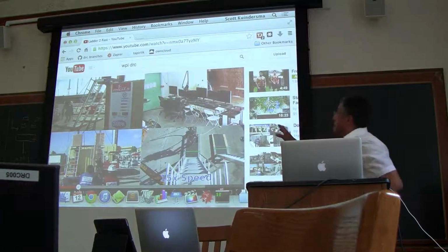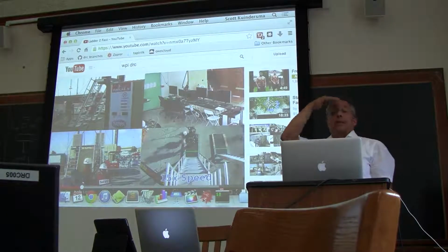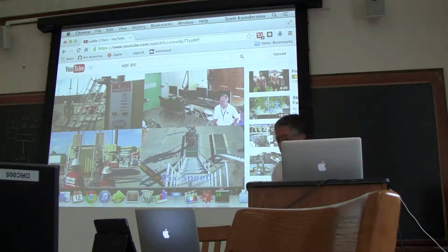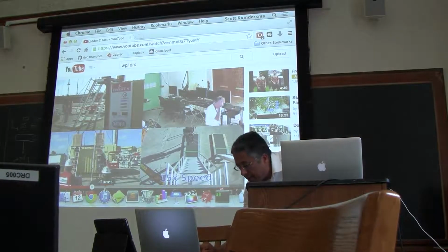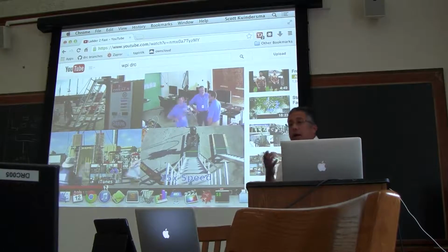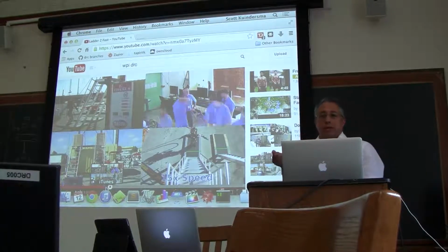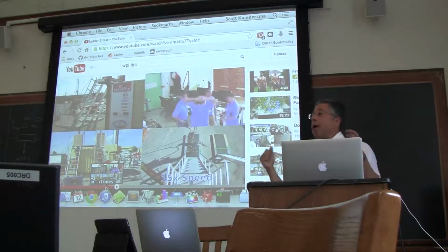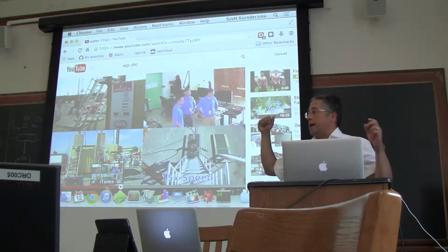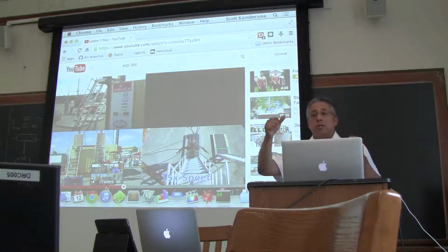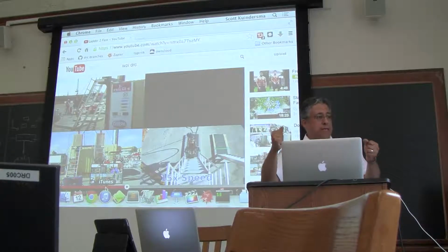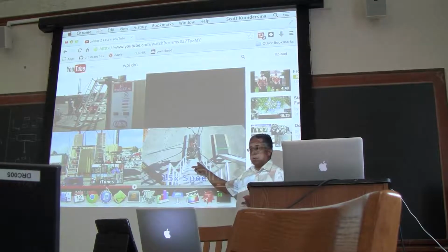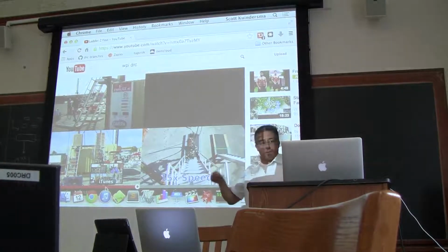What you see are the official videos taken by DARPA during our ladder task. One of the key things that our team members came up with was called nudging. In the team, we were calling it nudging. So what it was: the robot calculates and executes a scripted motion. Let's say for the ladder, we were relying on holding onto the steps to pull the robot up, to be able to climb up.